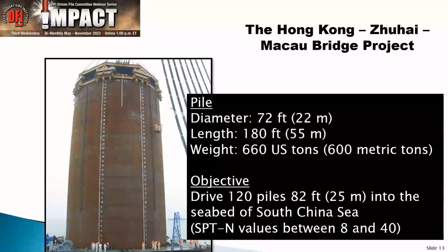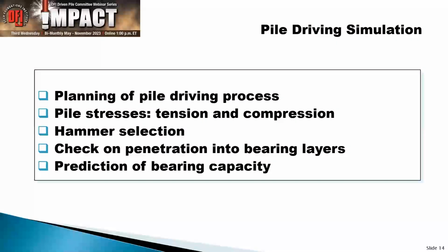And then the other problem that we started to realize is that when you have a pile that is 72 feet, what one side of the pile sees and what the other side sees is not necessarily the same thing. But we started looking at our design methodologies and started thinking, okay, what should we be doing here? And we said, okay, fine, let's just do pile driving simulations. Just what you're doing when you have a pile with an impact hammer. You plan your pile driving process.